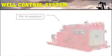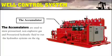Now, the well control system consists of three major parts. The first part is the accumulator. The accumulators are used to store pressurized non-explosive gas and pressurized hydraulic fluid to run the hydraulic systems on the rig. The accumulators store enough compressed energy to operate the blowout preventers even if the power system of the rig is not operating.